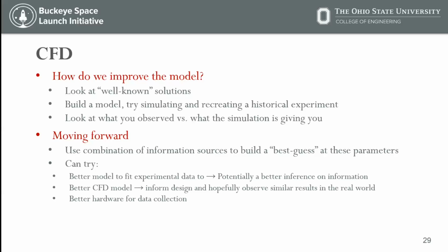And if you want to go further, like you were saying, there's wind in real life. So you're not always going to be going straight up and straight down. You might be turning a little bit, and that's going to affect your flight, and that's going to increase the drag that you see. If you're taking data based off the accelerometer data, if you're not going straight up, you can't really trust the accelerometers. You have to go off of pressure stuff.